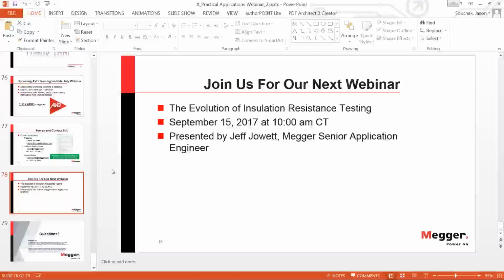And in the end, it all comes down to what Jason said at the end. What is your plan? Why do you do testing? If you do it because of cable replacement, then you're typically only interested in the aging condition. If you are really interested in making sure that these circuits have high reliability, you have to do a global and a local test, a combination of both, which could be tan delta and partial discharge. That's probably the most common way to do it today.